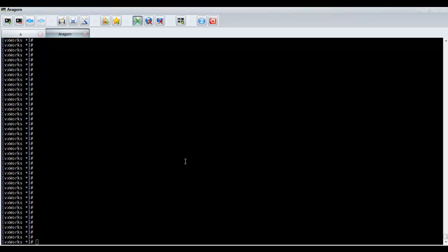What I'm going to show now is essentially the same process of connecting to the DTP4500 and deploying an application. But this time, instead of using the SCA monitor in Spectra CX, I will perform all of those actions using the Oeadmin tool that comes with the Spectra core framework. I still have the DTP4500 board running, and it is running the platform model.